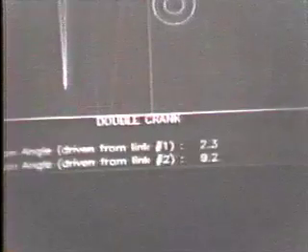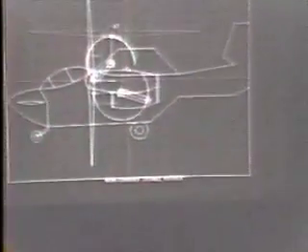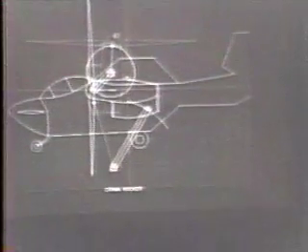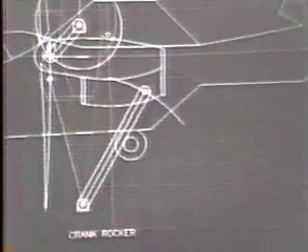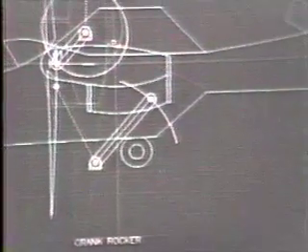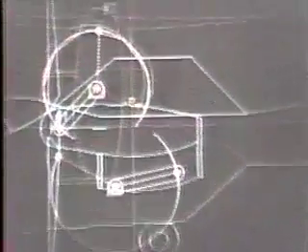Arcs show the limits of crank rotation or the limits of rocker swing. The Grashof type for the mechanism is flashed at the bottom of the screen, as is the transmission angle for the mechanism being instantaneously examined. All of this takes place in real time.